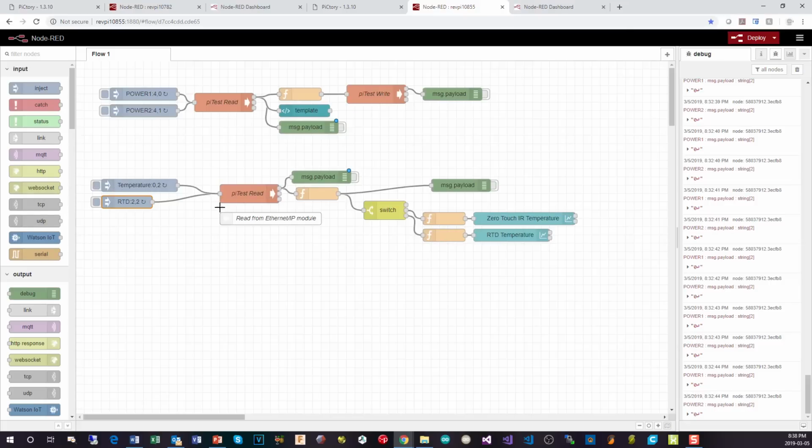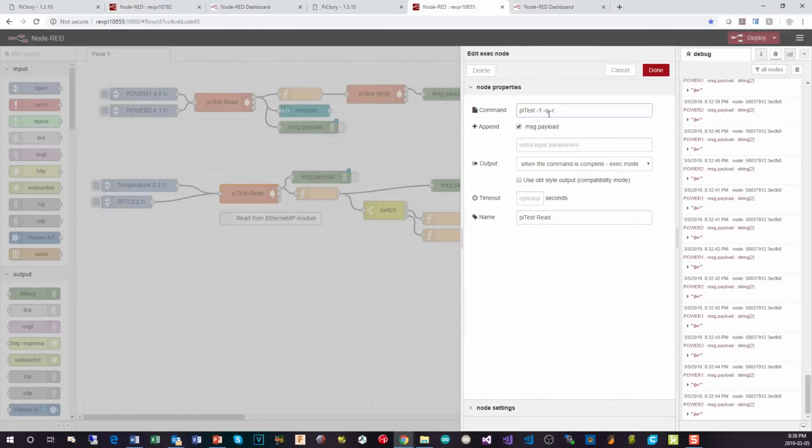So that's going to go into this read, which is doing the -R. Now if you've got -R, comma, and then just a 0 or a 2, it'll read the full byte, but only 1 byte. If you put a comma and then a value after it, it will read 2 bytes. You tell it the quantity, basically. If you put a name here of a variable, then it's just going to read the variable and you can't do anything else with it.